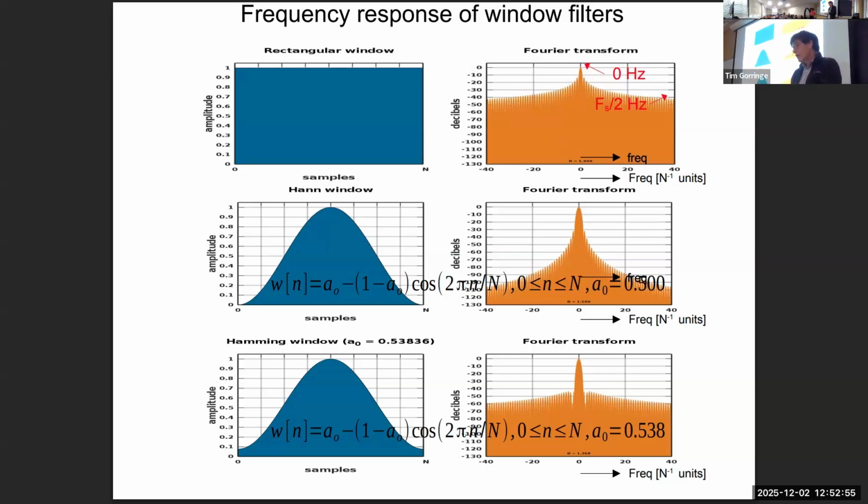And likewise for 3 cycles in the filter, or 4 cycles, or 5 cycles, those signals at those particular frequencies that are harmonics of the window size won't get through the filter. And so that's the cause for this sort of fine structure, this high frequency pattern in this upper plot here. It's a little bit more complicated when you're not weighting equally, but you can imagine that it still applies when you're not weighting equally. So you see the patterns here.